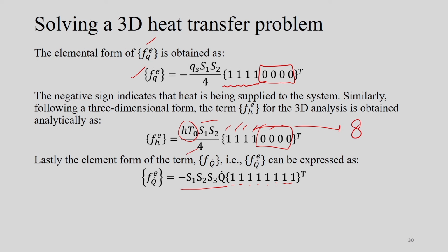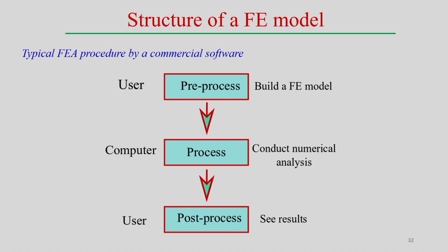Once it is done for one single element, we make a loop over the elements and put the contribution from each node point at its global position. Then we make a big matrix depending upon the node numbers of the whole solution domain. For example, the whole solution domain may have 100 node points, but one element may have only 8 node points. We construct the matrices for the 8 node points, then place them into a 100 by 100 matrix, because that is the global numbering of the node points. We put the contribution at the global number of each node and assemble, and finally it becomes a 100 by 100 matrix. It is then in the form Ax = b, and we solve this linear system of equations to get the variable. This is the usual procedure of finite element.